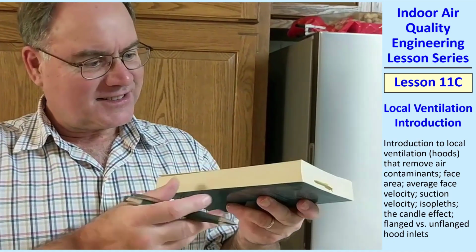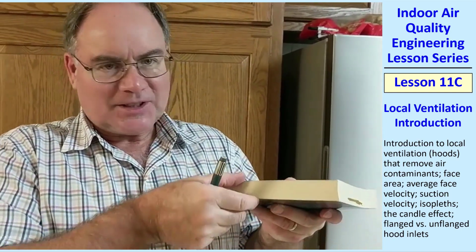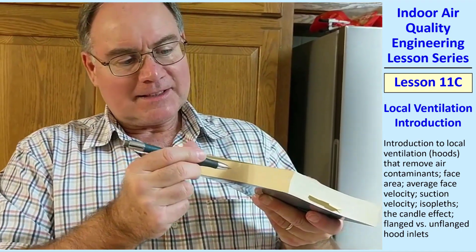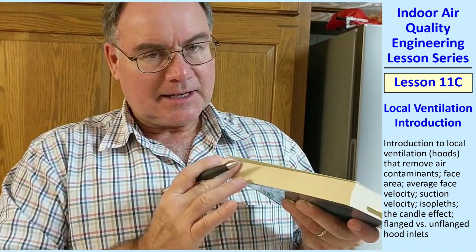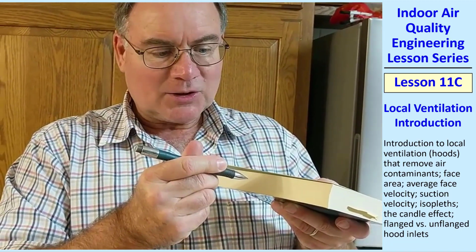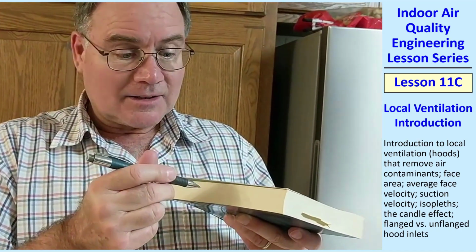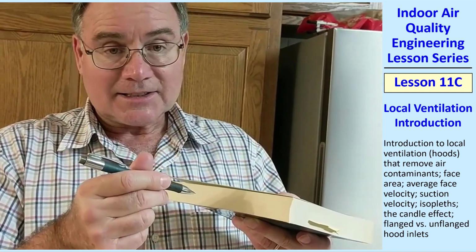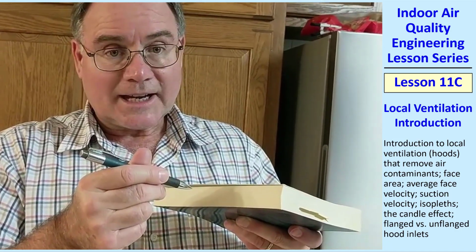This book has about a 10-to-1 aspect ratio. So if we pretend that this white portion here is a slot, that's a suction, and I put a probe right in the center line and approximately one slot from the inlet, pretend this is the inlet, about here, the speed is only about 22% of the average face speed through that slot. So you see that it decays very rapidly. If you go out 2 slot distances away, right in the middle, it's about 10%. So it really decays rapidly.